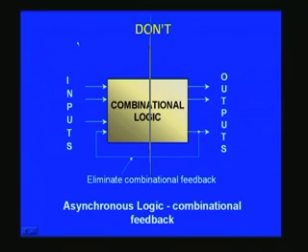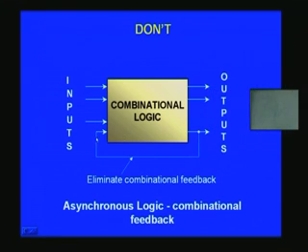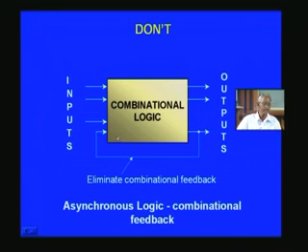And the common mistake that we do make is to take a combinational output and feed it back, and this is detrimental in making a chip as such, because for example, if you apply a 0 at the input here, and the combinational logic might produce a 1 here, and then 1 being fed back, it keeps on rapidly switching from one state to another, and this will be uncontrollable as such, and thereby it will not work in the ultimate chip that you have designed. And furthermore, this may be rejected at the synthesis level itself.